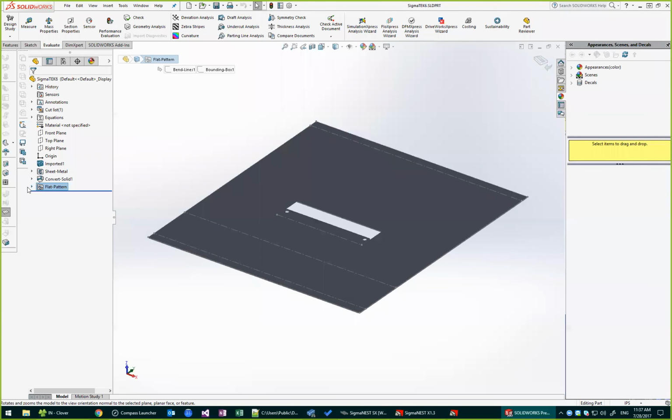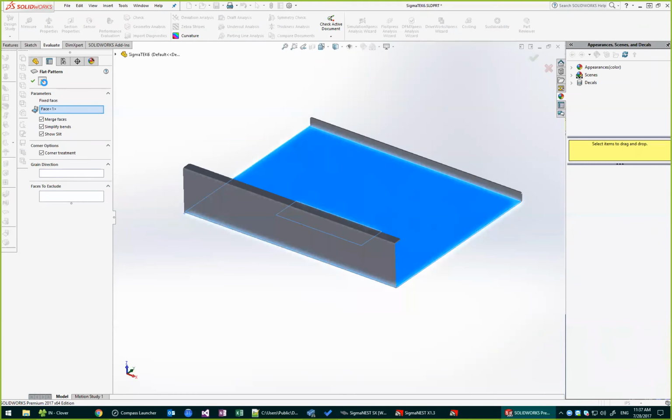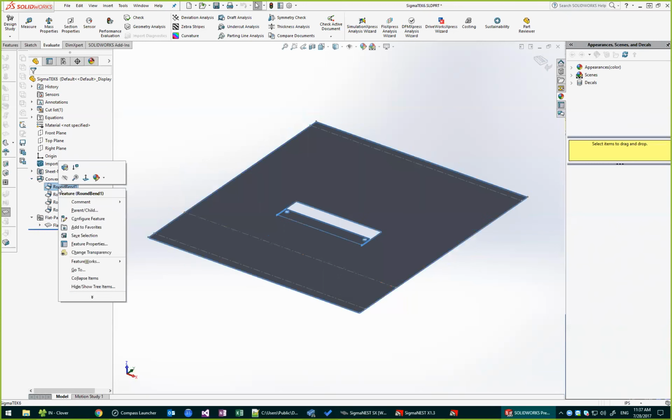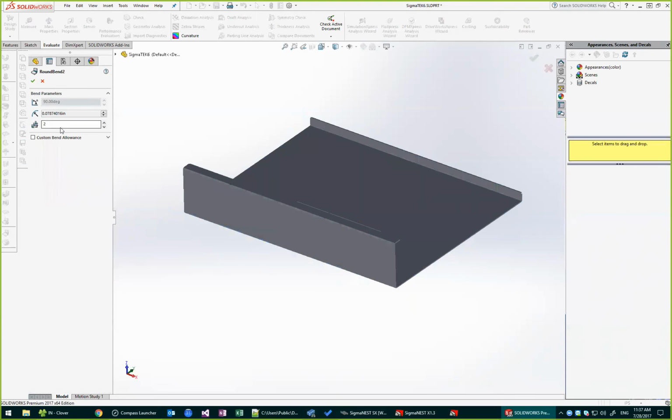Additionally, over here, let me actually go to bends. That's not that bend, this bend. So the bend radius used here is based off of the material that was set on the SolidWorks part, or possibly a custom one. I just wanted to point out that differentiation: what is set for SolidWorks, and then the flat pattern that it has, is what SigmaNEST will use when you have a sheet metal part.